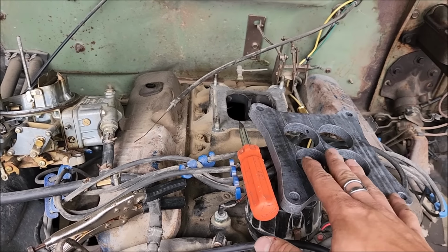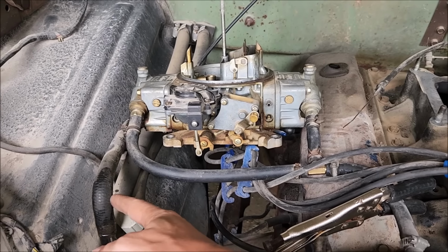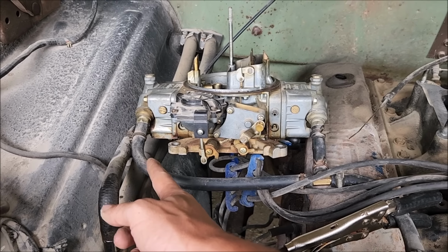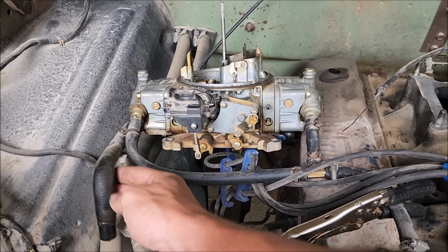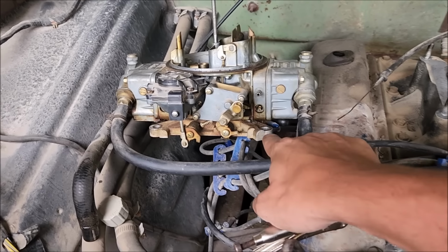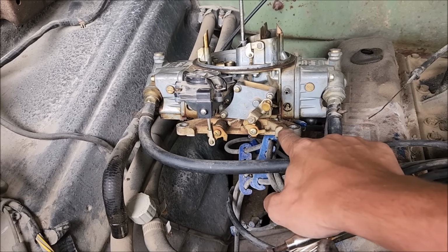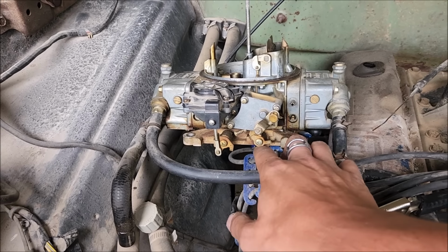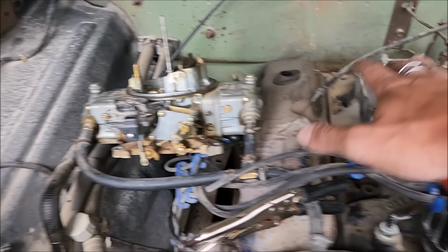This black capped one I'm pointing to here, and then the one where the PCV valve is hooked in back here. You always want your PCV on a dedicated, centralized vacuum port with nothing teed into it. This is plumbed into the center of the throttle blades, so it's not biasing to any one cylinder or another. That would be bad. So it's the only thing on this vacuum line.